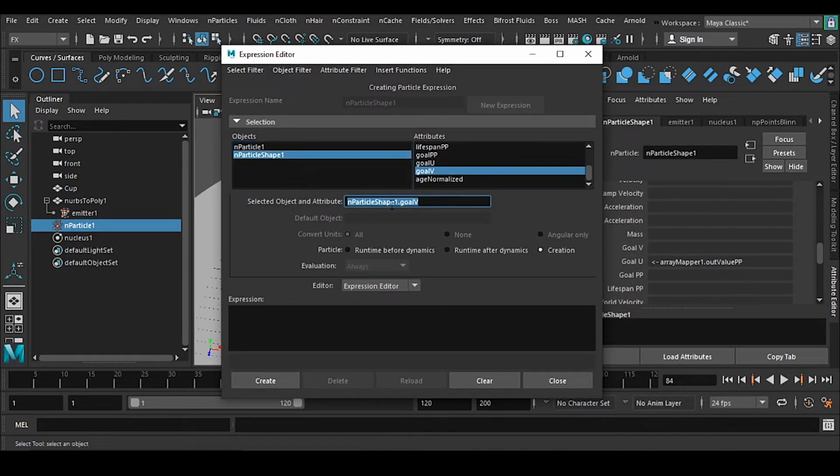Just simple copy, middle mouse drag and drop, the shortcut of the copy thing, and space, and an equal sign, space, R-A-N-D, rand, a randomness you can say, and shift 9, that means the bracket, 1 comma 0, shift 0, that means the bracket, and create.